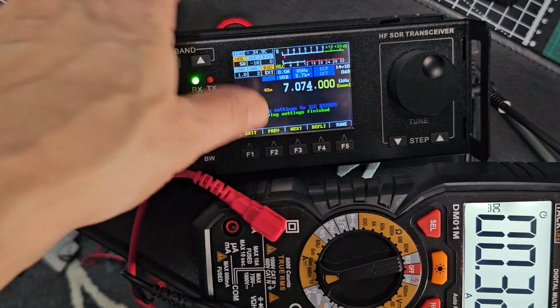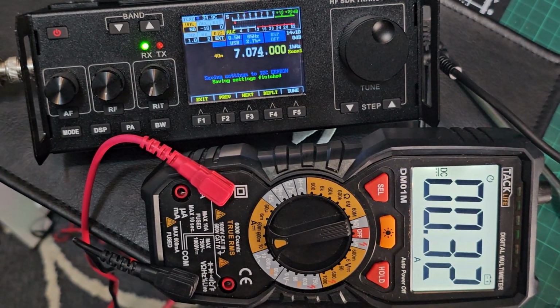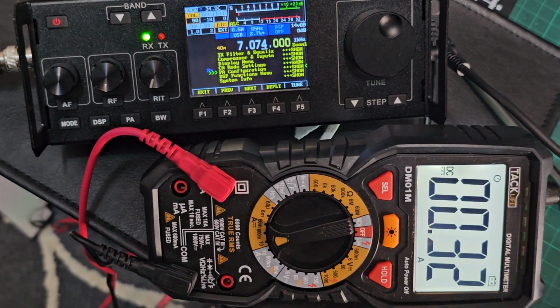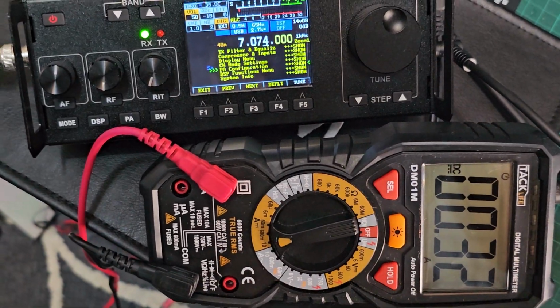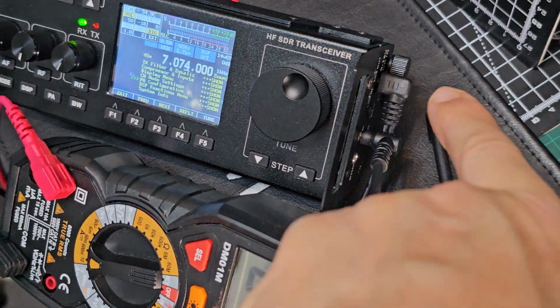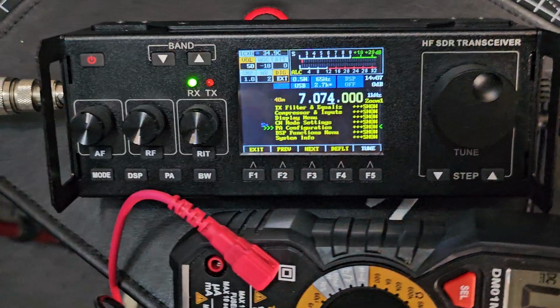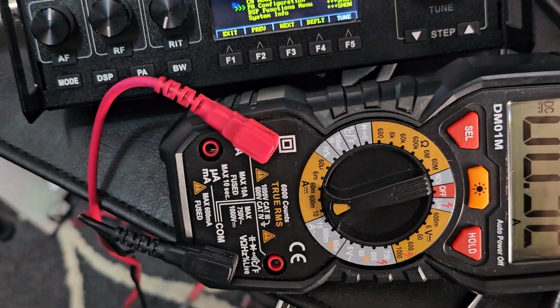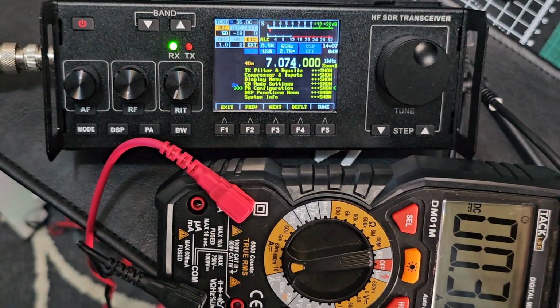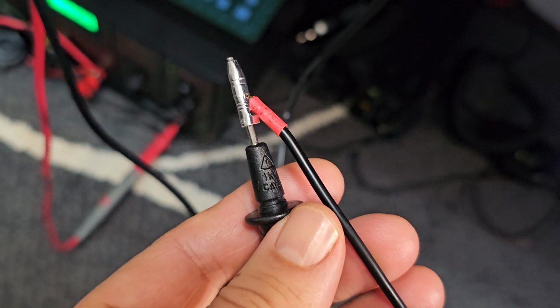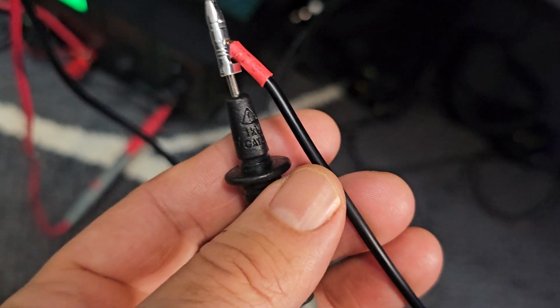Let's set the PA bias on our RS-918. We've got our amp meter in line already. We've spliced the live coming out of the RS-918 and we've connected the live and the earth to my power supply. So the live cable, I know it's a black cable, but it's actually live.